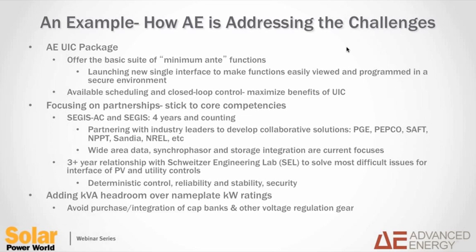And then one other thing that we're doing is investigating and adding kVA headroom over our rated kilowatt capacity. What that allows for is the ability to operate at a wider power factor range without really sacrificing energy harvest. Power factor control is becoming much more predominant, and from an energy harvest point of view, we don't want any sacrifices there. So that's definitely an area that we're investing in as well.